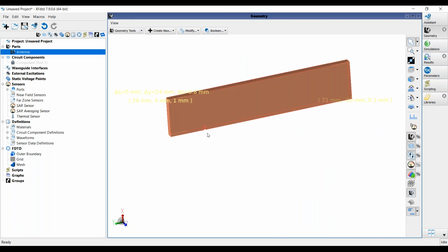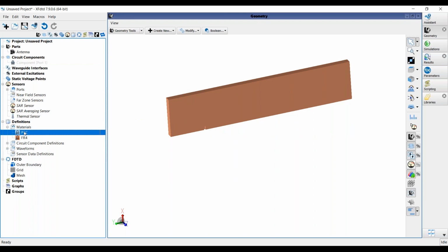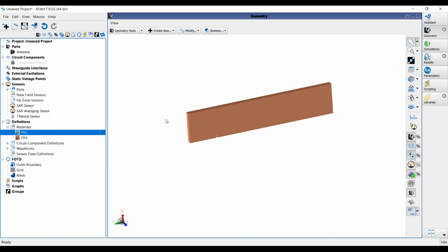cutout, which gives the information to the user on how to align this geometry and where exactly the feed is located. But he doesn't get any other information related to what materials are being used, what the mesh properties are, and all of the results or the outputs related to these geometries are also encrypted. The mesh related information will not be available to the user who is trying to use this geometry in his CAD models.